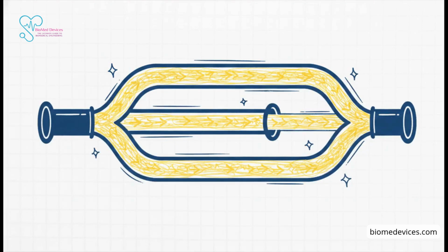It all comes down to first principles. In a parallel circuit, the total resistance is actually always less than the resistance of the smallest individual resistor. Why? Because every single time you add a new parallel branch, you're opening up a brand new path for the electrons to travel down. Even if that new path has a lot of resistance, it's still an extra road, and more roads mean it is generally easier for the total traffic to flow. So mathematically, adding individual resistances in parallel actually diminishes the total equivalent resistance.